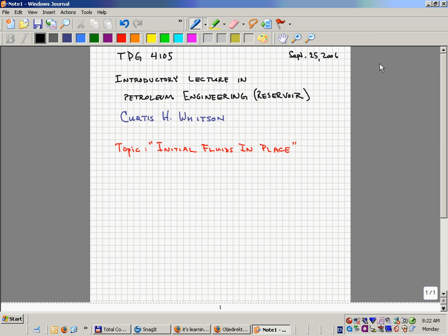In the Ekofisk field, we're injecting hundreds of thousands of barrels of water into that field, into this chalk, and it's pushing the oil out. Okay? So this is just as important, and it looks just like this when you get it cleaned up. Chalk. Permeability is around anywhere from 0.1 millidarcy to 5 millidarcies.